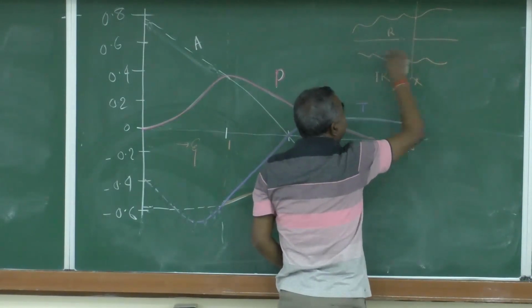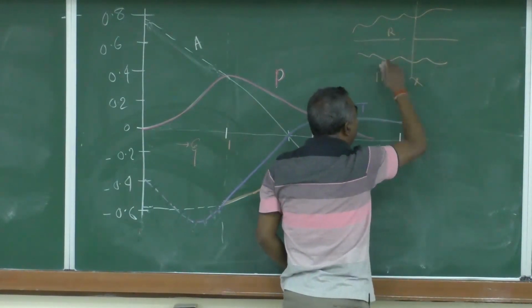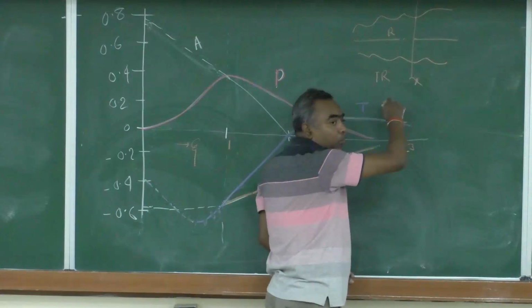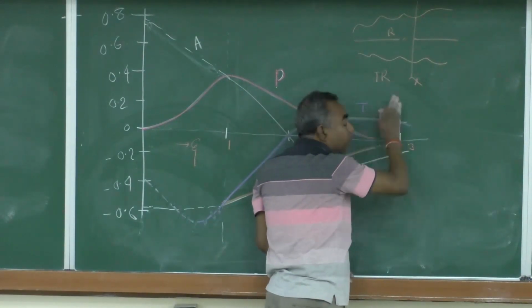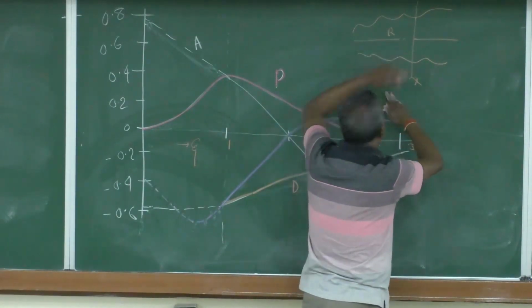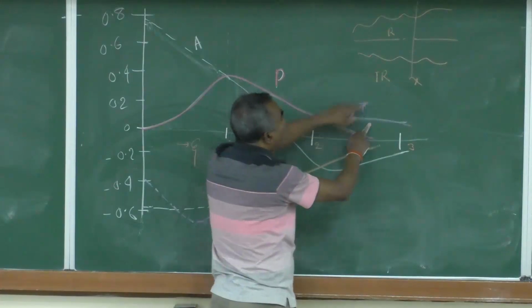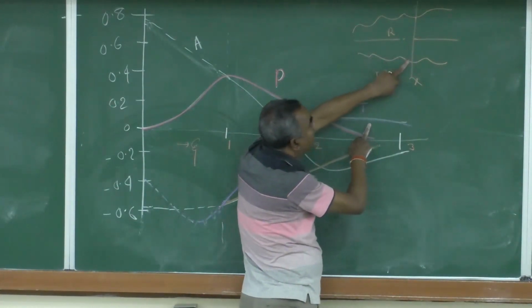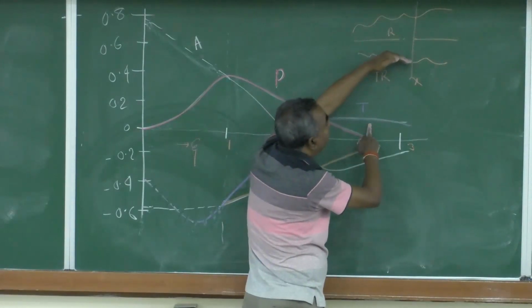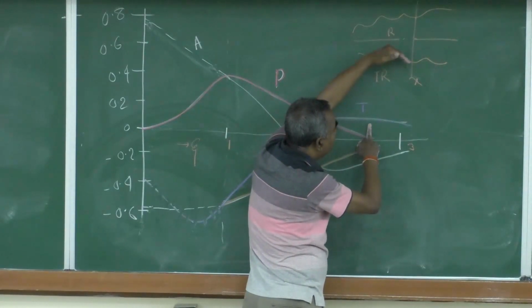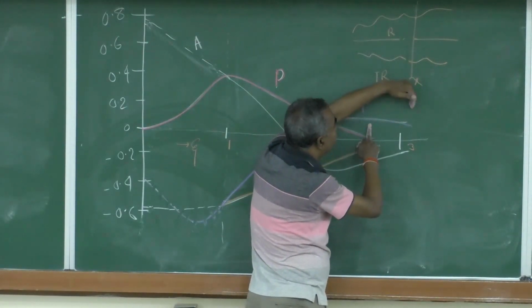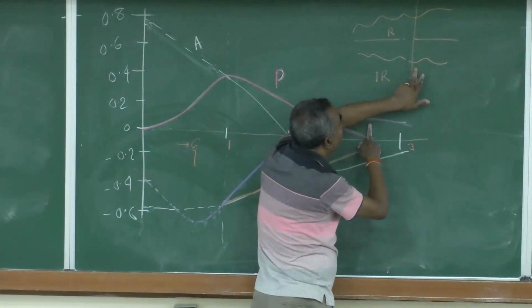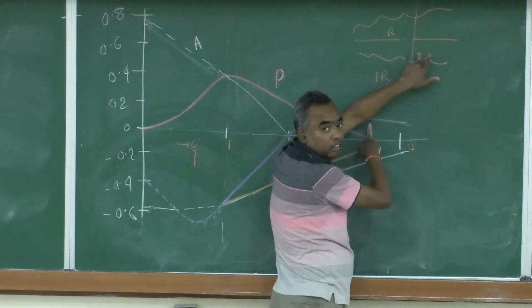Inside, the flow is turbulent, so it is rotational; outside, the flow is not turbulent, so the flow is considered to be irrotational outside. That means this transport term is carrying energy from the central line towards the outer side. That means the wake is actually propagating towards the irrotational side, meaning the irrotational flow is entraining inside the turbulent flow.